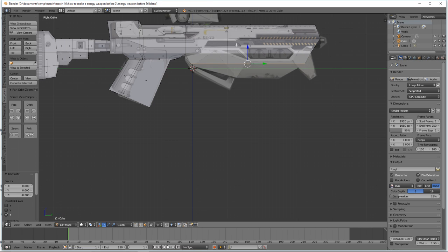Okay, we're going to put a loop cut right here. I'm going to hold control, and then while holding control, press R. I'm then going to left click 1 time. Because I left click 1 time, I can move this loop cut. I'm going to put this here. I prefer for this line to be straight, so I'm going to press S to scale on the Y axis 0. Then left click to lock that in.